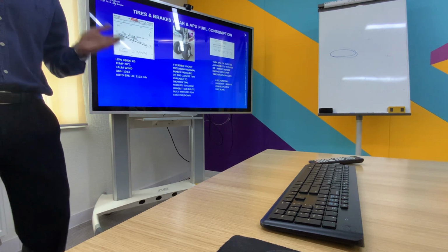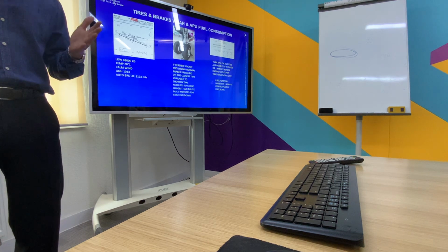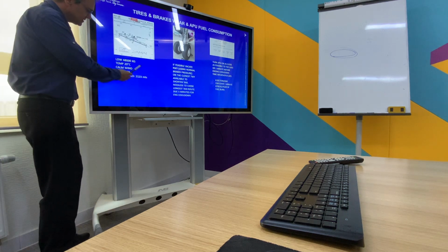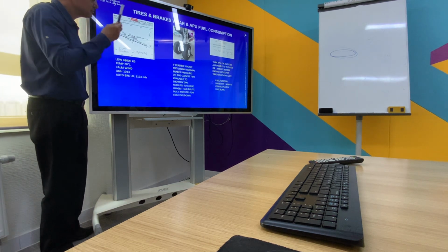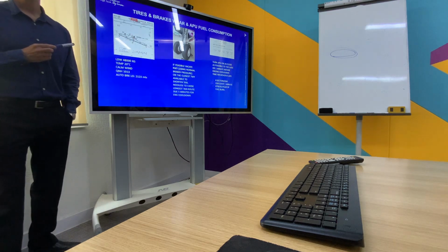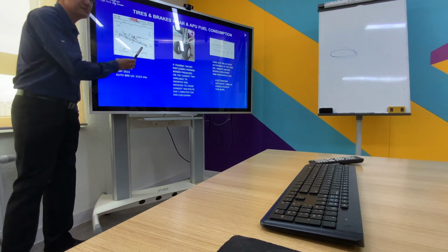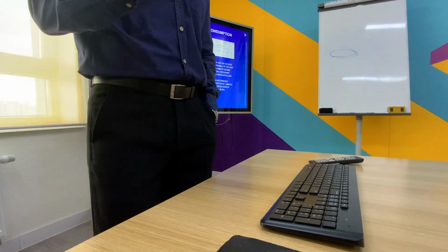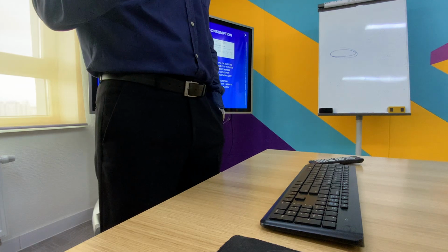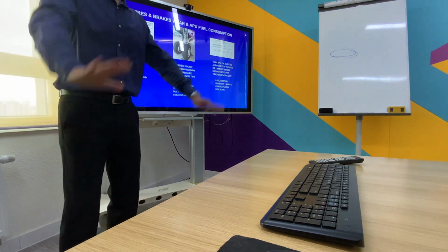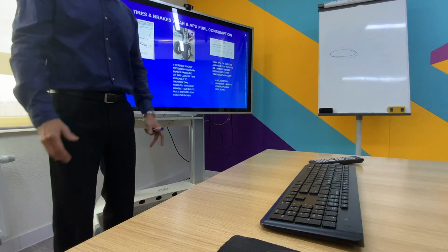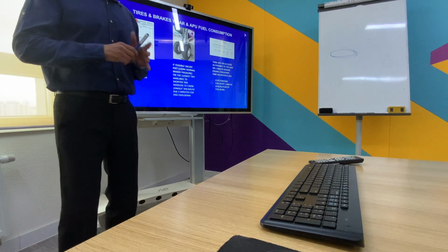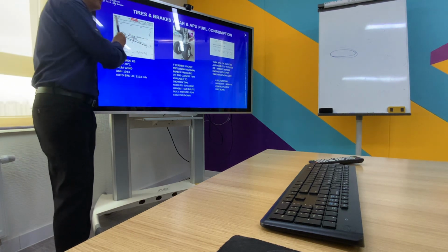But normally, I will press the brakes before. In this situation, is it feasible to vacate via Charlie? I have 1,800 meters. If you touch down on the touchdown zone mark, it's feasible. Really feasible. I'm not talking about pressing the brakes with strong force, I'm talking about normal brake usage. It's feasible to vacate on Charlie.